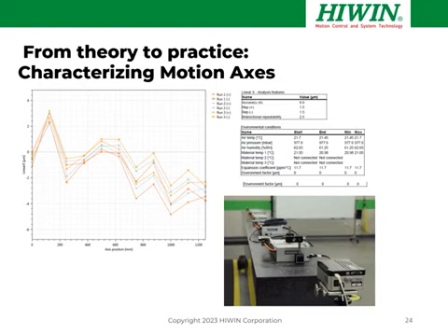So a benefit of working with an experienced motion systems company is that they will have these instruments and they'll know how to use them, because proper setup of the optics is critical to getting good data. And ultimately, these tools provide the performance test data in an easy to understand report so that you can see exactly what kind of behavior you're getting. And then you can use that data to error map or compensate your system.